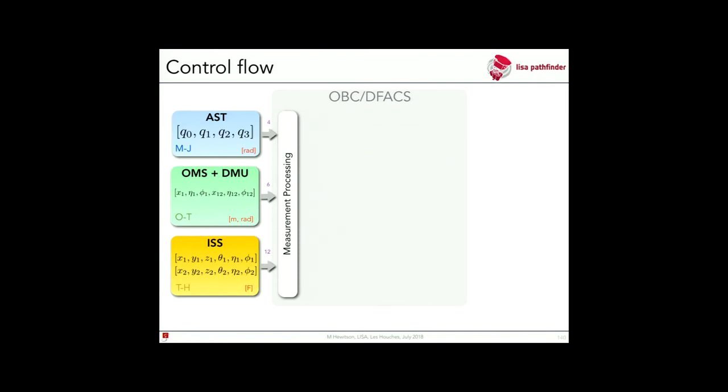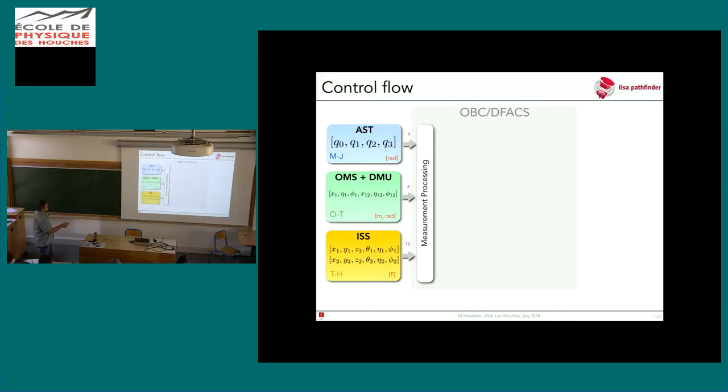We then have this drag-free control system, which is a big computer program effectively. Those sensor outputs are all processed, partly to calibrate, partly to decorrelate or rotate them to correct for any kind of misalignments. And then there's a sensor mapping scheme. We have more measurements than we need, because there's redundancy between these 2 systems, and so you have to make a choice of which measurements you use for which degrees of freedom.